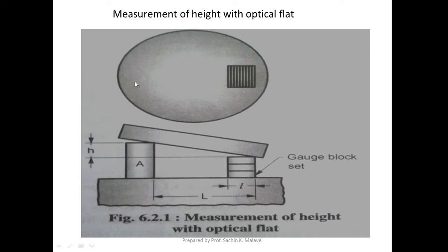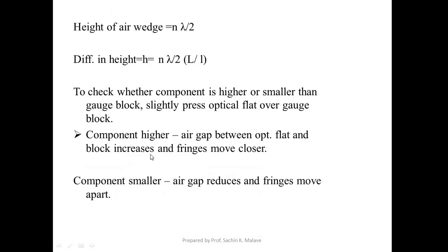As this side goes up, the air wedge will increase, isn't it? So when the component is higher, the air gap between the optical flat and block increases, isn't it?